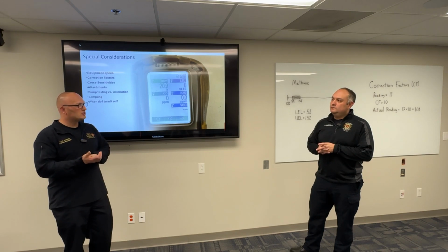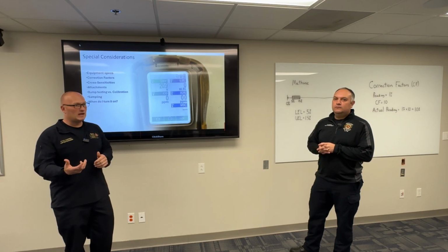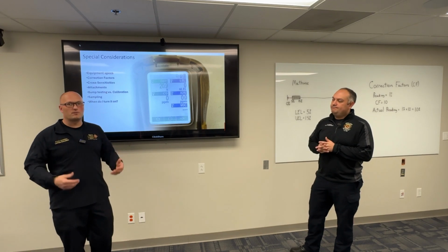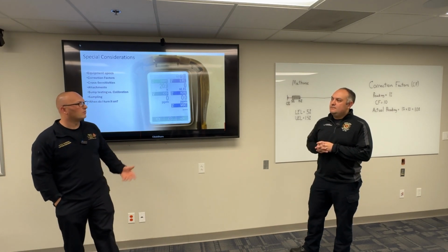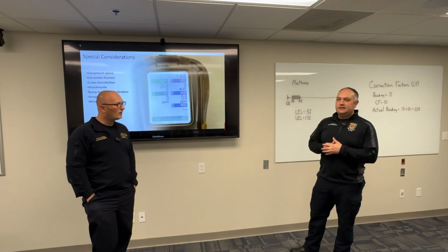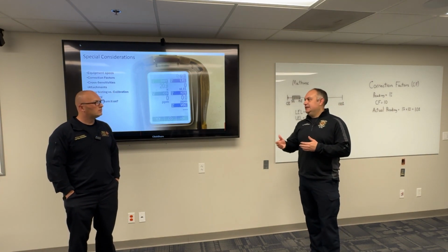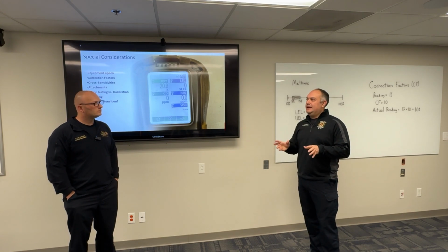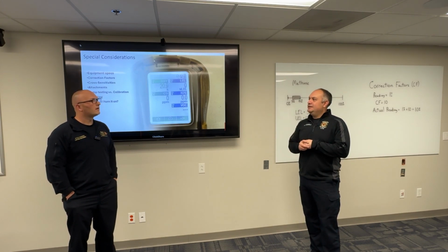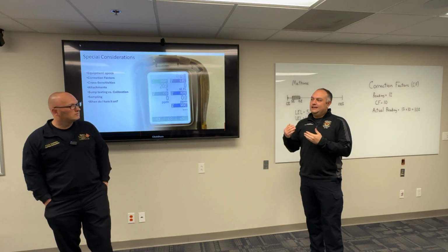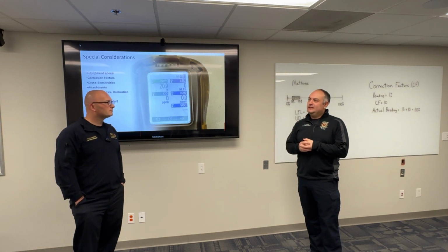If you have that situation, it might be worth just waiting till you get on the call and actually turning this thing on in the front yard and letting it get a true fresh air calibration, so I'm not riding down the road. Right. And that's important because these sensors need time to warm up. They need time to do, like you said, the fresh air cal, because if you don't do that right, all your readings after that are going to be inaccurate, possibly. So very important to do that stuff. And I know it sucks, but you just got to be patient with it and let it do its thing.